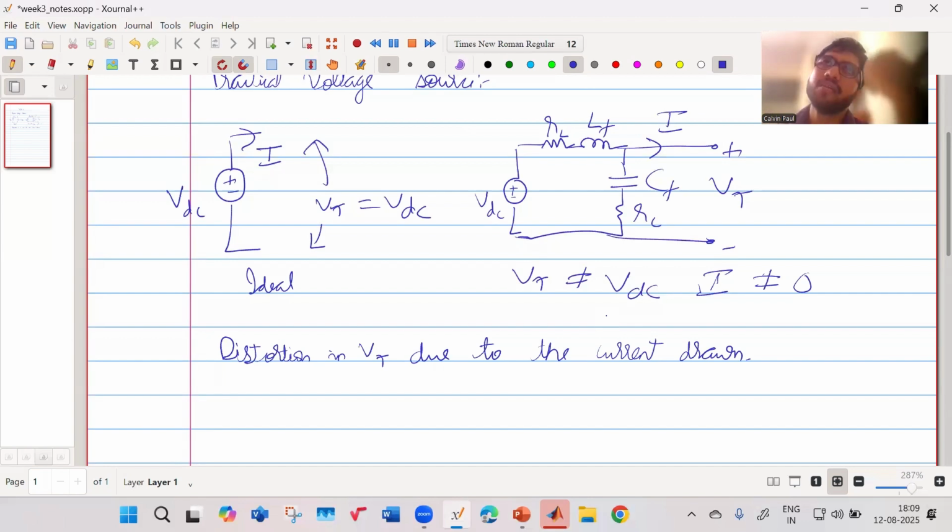You guys might have seen this example. Let us say we switch on some large motor or some large electric load in our house. Sometimes the lights will dim for some short period of time. Why is that? Because when you're turning on a motor or some electrical appliance, there is no back EMF there.